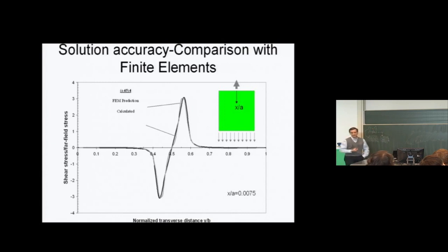Now this is telling us that whatever these shear stresses do, it happens only 0.3 away from the one end and up to 0.7 or 0.6 or so, between 0.35 and 0.6, whatever. It's only in this region that the shear stresses are significant. So as far as the reinforcement in the transverse direction along the y coordinate, we would only need to reinforce the center of the plate, which you would expect because the point load is at the center.